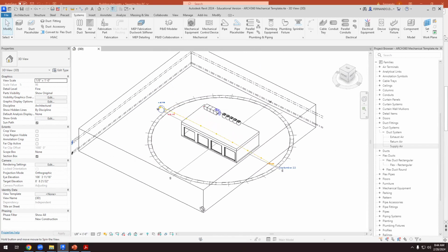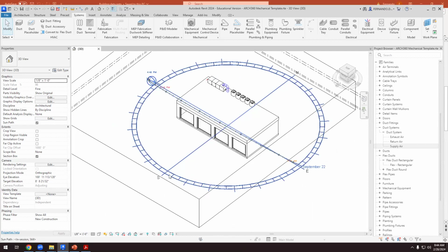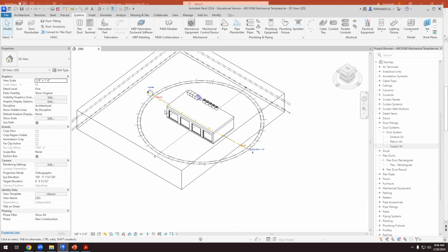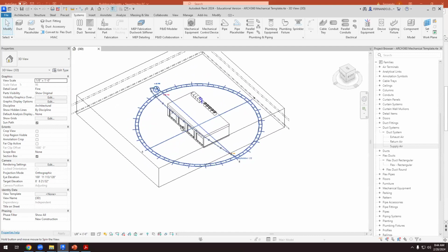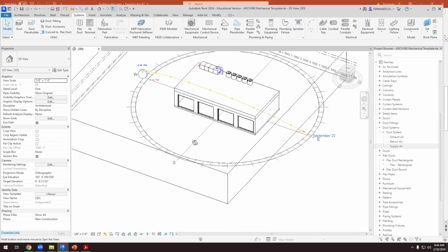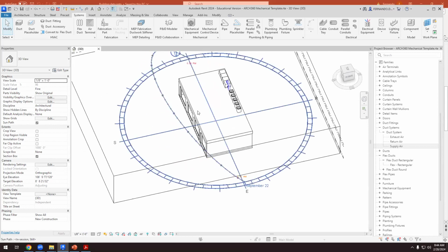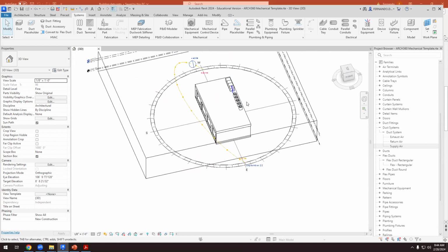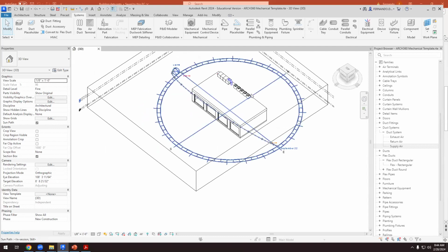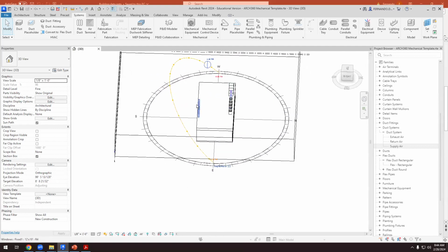This is important because we need to know where the south is. We have to select the right orientation for the PV panels. The PV panels are quite expensive and they work well if they are facing south. If we have the wrong orientation, placing PV panels doesn't work. We're spending a lot of money and we're not getting anything from it. So what was my decision? I'm going to place all these close to the north facade, or the north part of the roof.